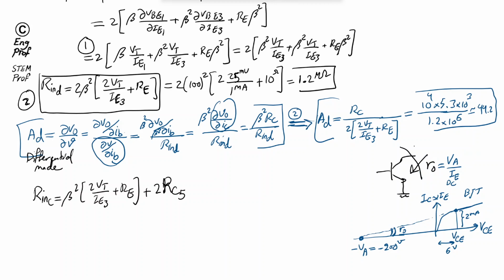But when we have a resistor in the emitter, things become a little bit more complicated. It's not difficult to calculate, but we have effectively a resistor in the base, AC wise. We have a resistor in the emitter, which in this example is 1.2 kilo ohm.